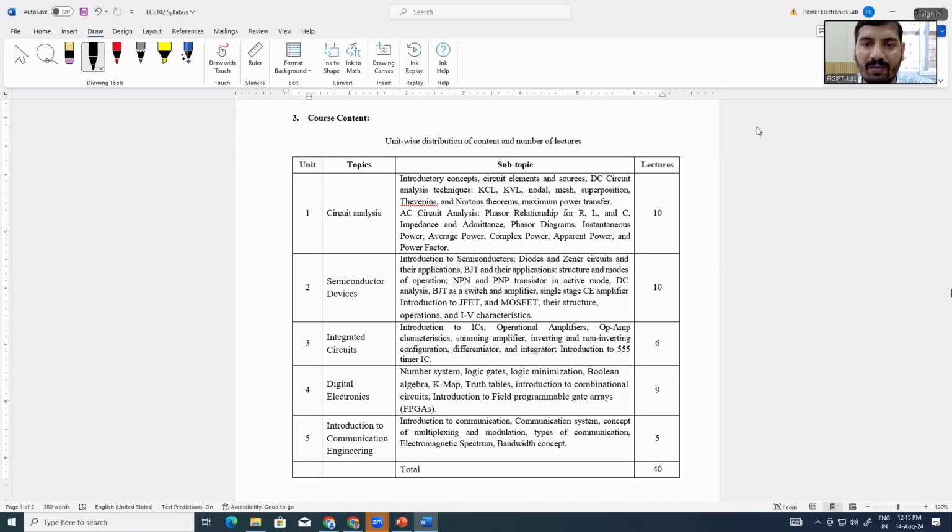After that, you have to study different types of network theorems that help to solve any complex circuit. The first one is the superposition theorem. You have to study only 4 theorems here. There are many more, but for your course 4 theorems are more than sufficient. By using the superposition theorem you can calculate voltage across any two terminals in the circuit and current flowing through the branch. Right?